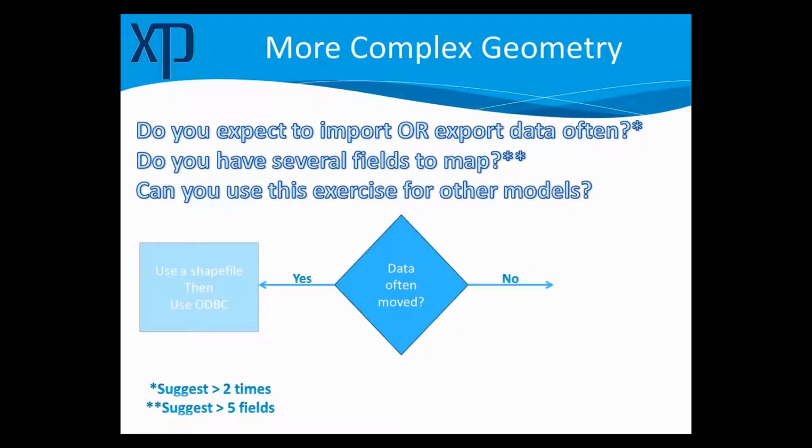fields. So if I have complex geometry and I plan to move the data often, I would use a shapefile for the geometry, and I would use a database for the data. If I'm not moving that often, I would probably just use a shapefile.